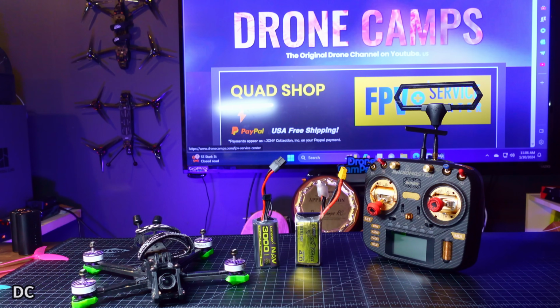Now, if you have a low kV motor, a lot of times a 6S rated motor under 2000 kV, the Li-ion pack on the left, as you see, is going to give you the longest flight time. A lot of these quads are advertised as long range type drones. So if you see a quad that's advertised as a long range drone, or an LR drone as we call them, that is a quad you can most likely try a Li-ion on. You can also fly a LiPo on a long range drone.